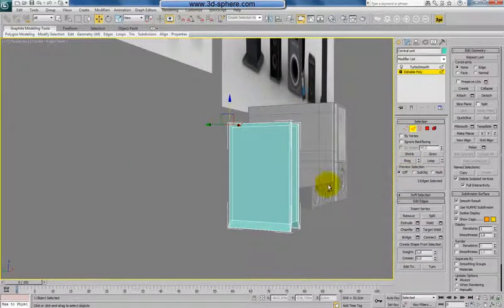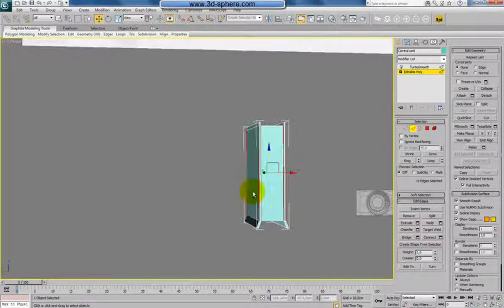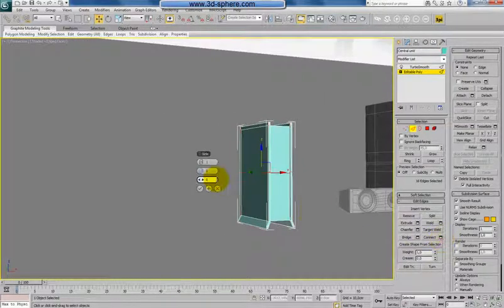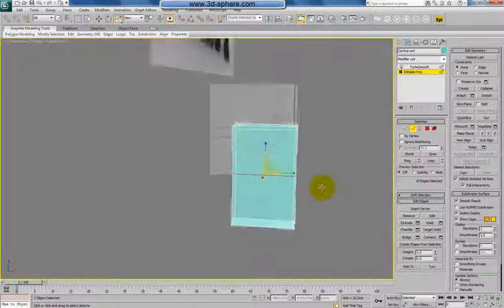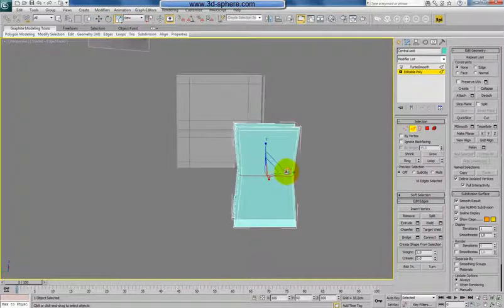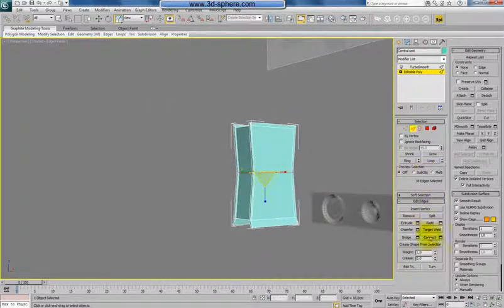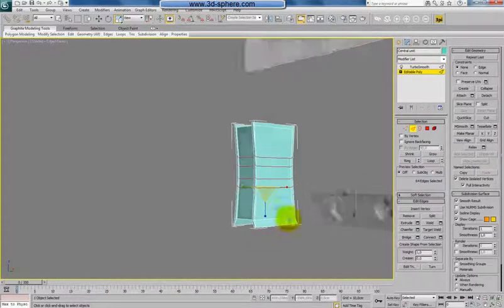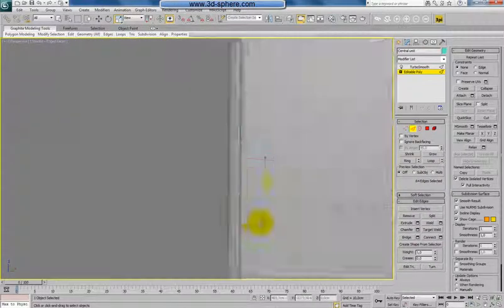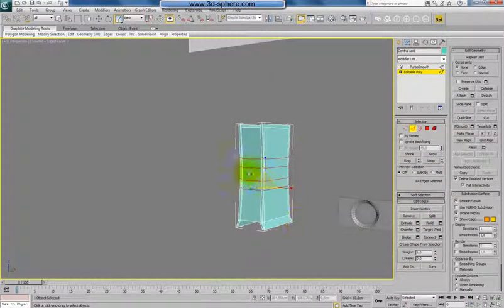I don't know. Okay, we'll do a different shape. So we'll connect this one here. We'll scale this in this axis. We'll apply a bigger chamfer like this and a second chamfer. So we make it kind of round here.